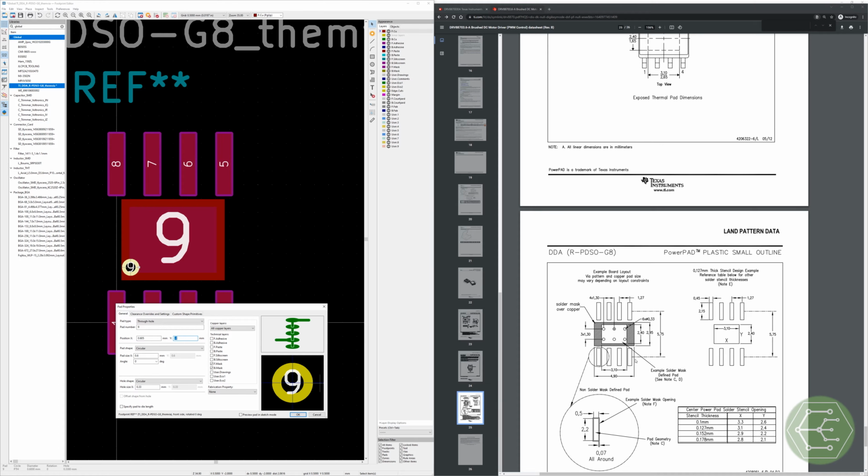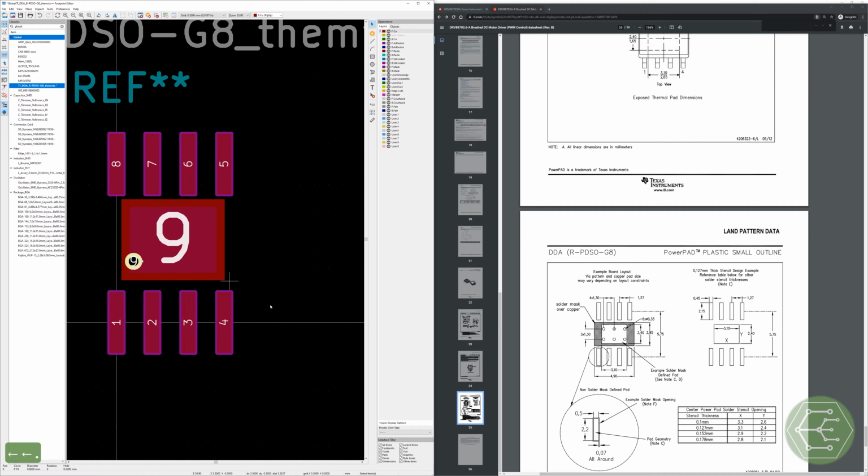That should get us to the center line from the center of the pad. So I'm going from here to here. That's what I'm hoping to do. That's 2.875 millimeters. Then we want to take off half of that 1.3. So we'll subtract 1.3 divided by 2, leaving us with negative 2.22 millimeters. See how that looks.